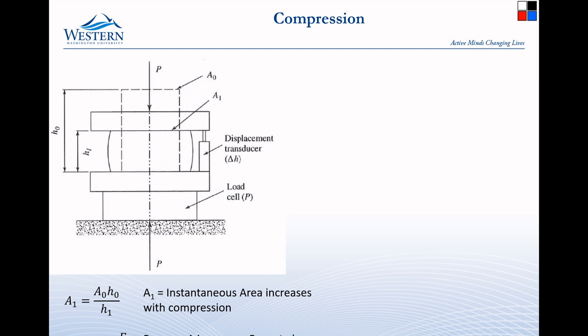As you squeeze them, they will start to barrel, they will bow out at the sides, the cross-section will increase. But when you actually get to the point of starting to plastically deform them, they don't fail by compression. They fail in shear.